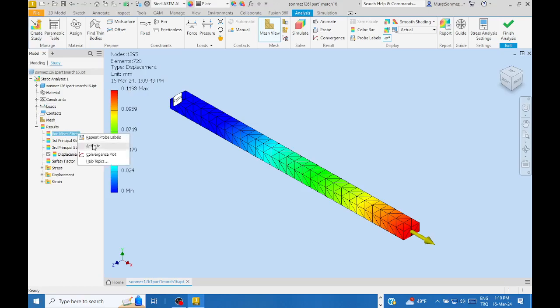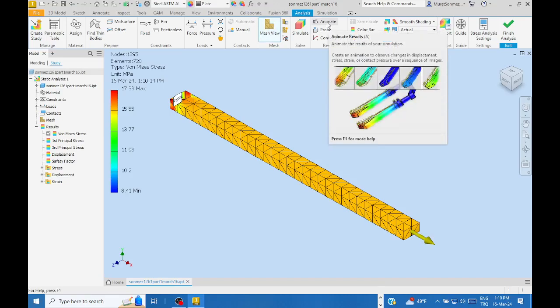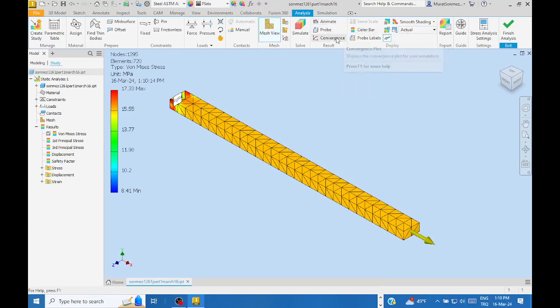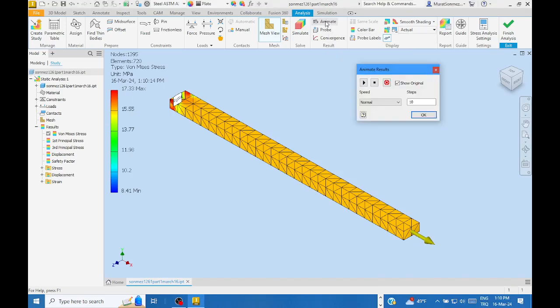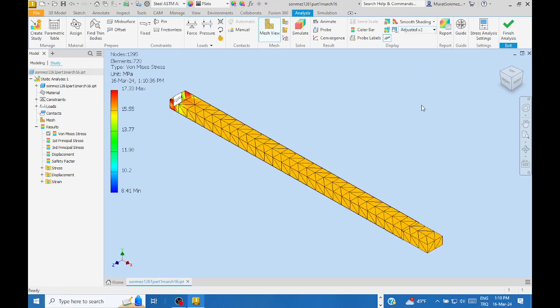And also, for making the analysis interesting for a layperson audience, be aware you can have a video film by clicking on the animate button. But first exaggerate the deformation using a zoom factor. And then animate.